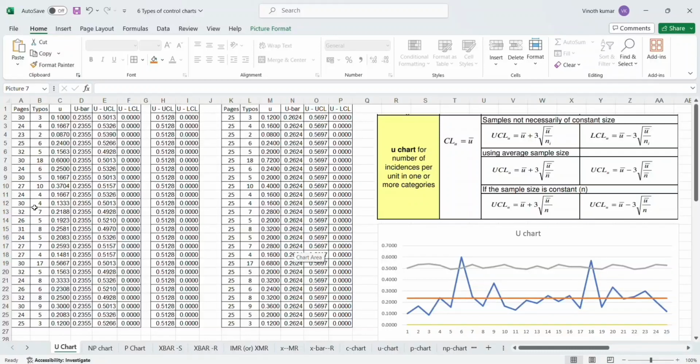A unit is getting produced, but within that unit, I have multiple opportunities to do a good job or a bad job. Then we can inspect 10 units, but we can end up with 15 defects. It's not defective, it is defects. Defective means the entire unit is called bad. Defects means within the unit I have 1, 2, 5 number of defects.